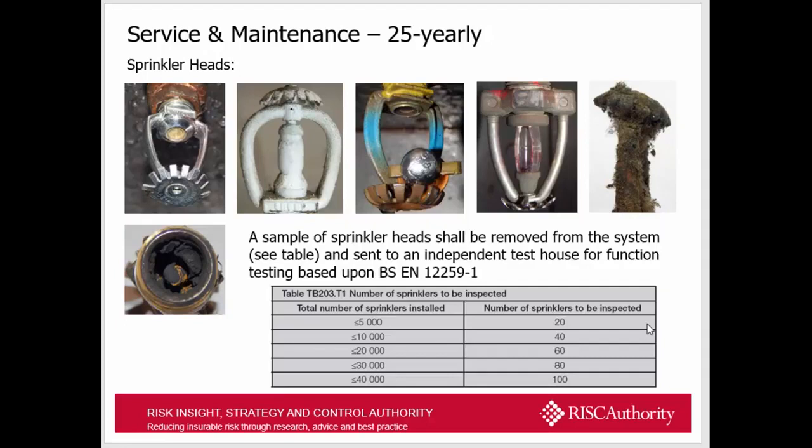The picture on the right is pretty self-explanatory. That needs to be removed and replaced, and the picture on the left is the reason why we take these sprinkler pipes and sprinkler heads out and send them away for testing, based on the condition that we find with regards to sprinkler heads and your sprinkler system.